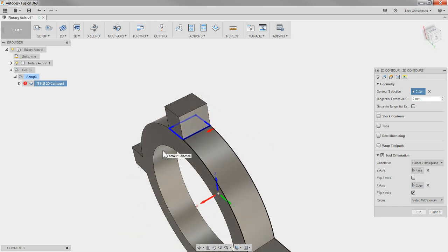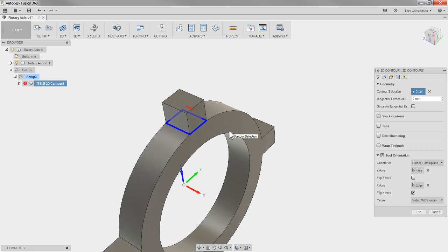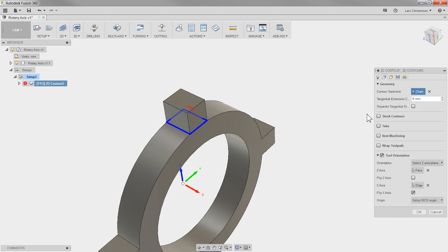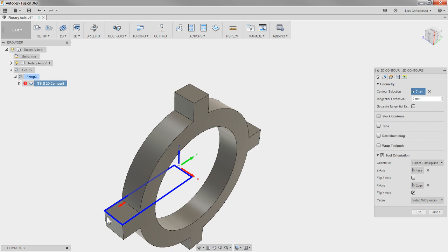That is the open contour selection. And it's extremely important that you know this, because anytime you have to select chains where all the edges are not on the same plane, this will let it project down. So let me just show it to you one more time. When I exit out of the chain here, it's like I never did anything. So when I select this edge, it automatically projects the closed contour, and it projects it down to here.